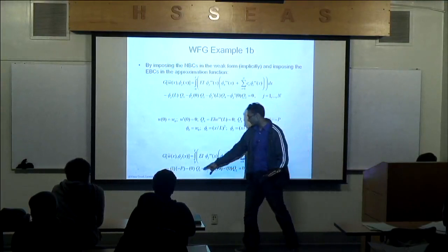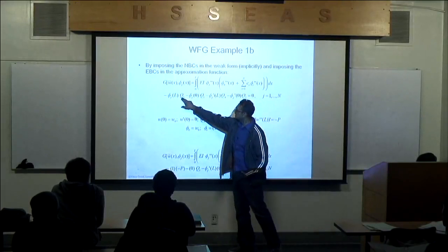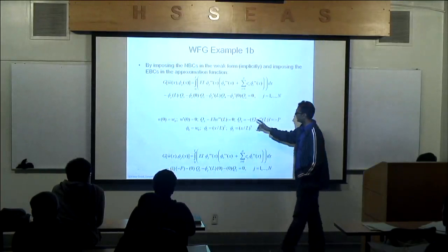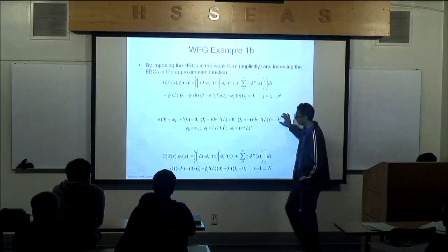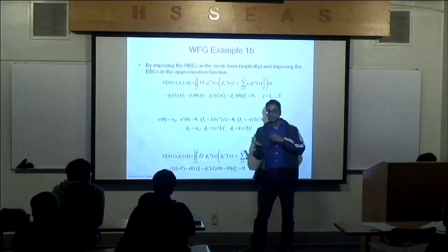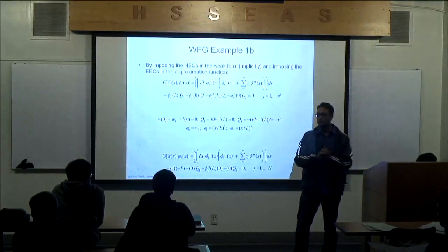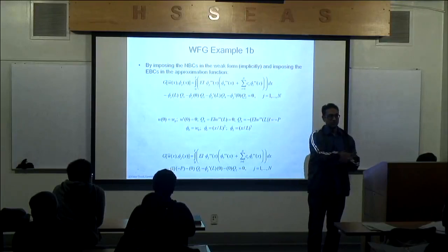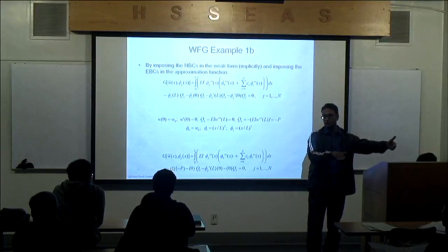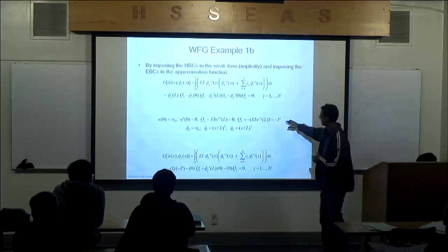This one is also multiplied by 0, so don't worry about that q. This one has a q3, and we know already that for q3 we're applying a load of minus p. So plug in the minus p directly in here. Do you see quickly that we're implicitly satisfying the natural boundary conditions by plugging that in directly? Implicitly. Explicitly, we're satisfying the essential boundary conditions through the approximation function, but implicitly, we're satisfying that natural boundary condition. So I'm plugging that in directly, minus p.